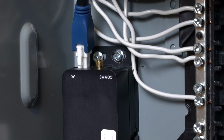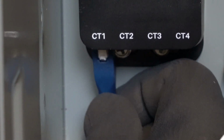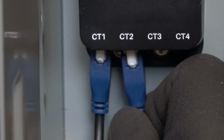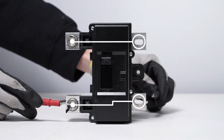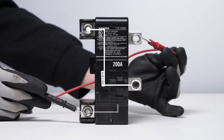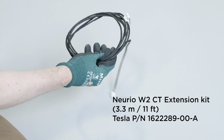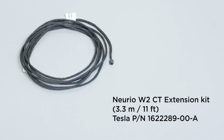Plug the voltage line harness into its port on the remote meter. Each lead on the voltage line harness corresponds to a CT port on the meter. Be diligent when measuring the polarity of the breakers. Remote CTs can be extended up to 15 feet with the use of one CT extension kit.